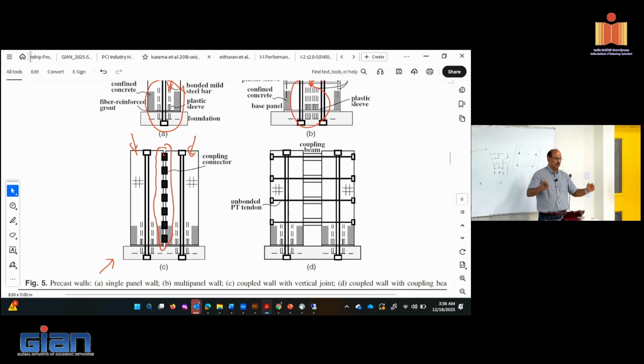So if a magnitude 7 earthquake comes along and you damage the building or damage the connectors, even though there will be aftershocks, typically I would argue that the post-tensioning should be designed so that structures can survive aftershocks without the couplers or without these coupling elements, and therefore you should be able to replace them right after the earthquake and bring the structure back to its original condition. So the jointed wall concept was born, something we promoted or investigated in the PRESSS program because it was very, very attractive.